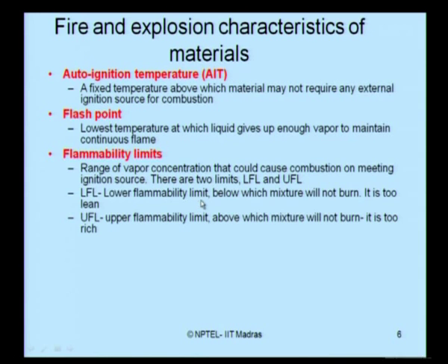Then the question comes subsequently, what do you understand by lower flammability limit? LFL is that limit below which the mixture will not burn, because the mixture will be considered too lean to burn. Upper flammability limit is that limit above which the mixture will again not burn, as it is considered to be too rich to burn.